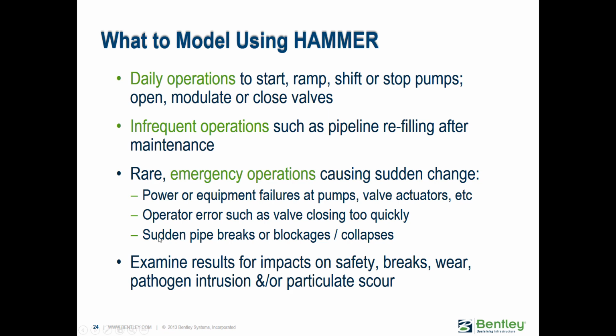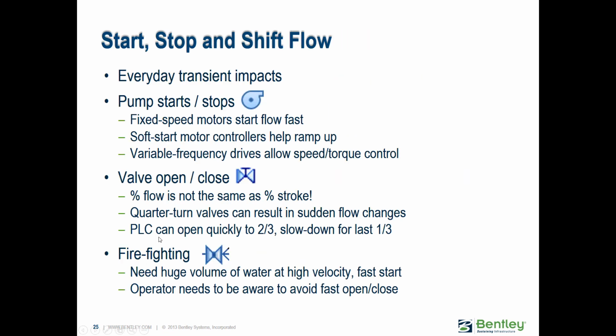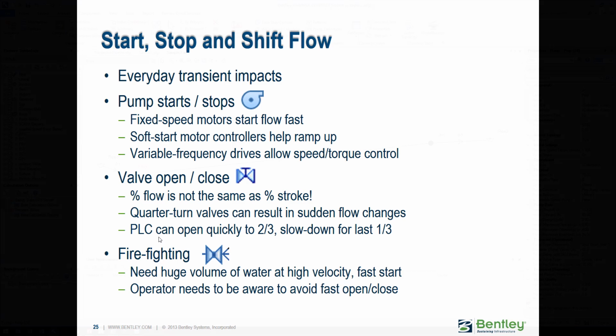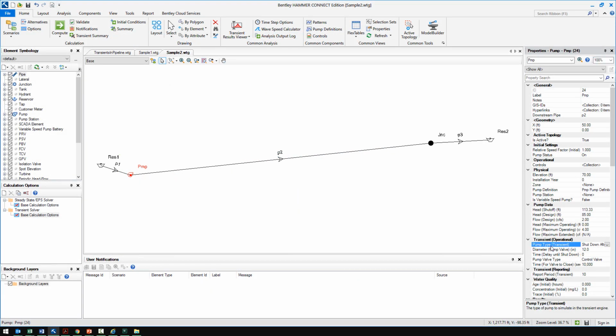So when we're talking about stopping, starting, and shifting flow, you would use the pump element there for your pump starts and stops. Basically, what we're saying here is that fixed speed motors start flow fast usually, but if you have a soft start motor, that can help control the ramp up. So you have to consider what type of pump you are modeling here, and how fast it will start up or stop.